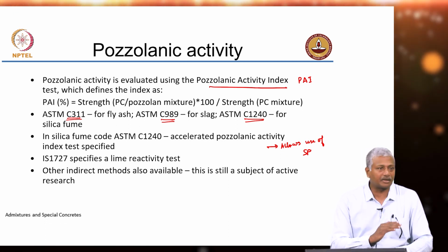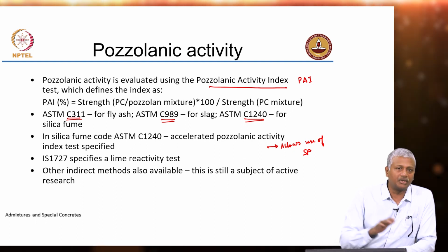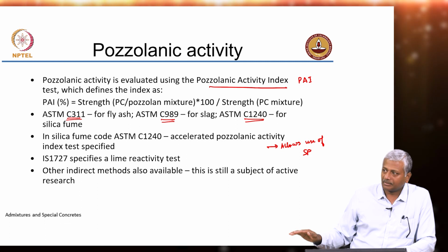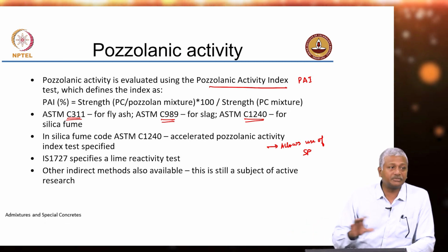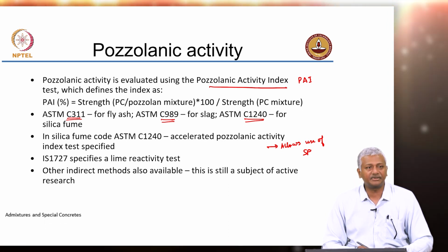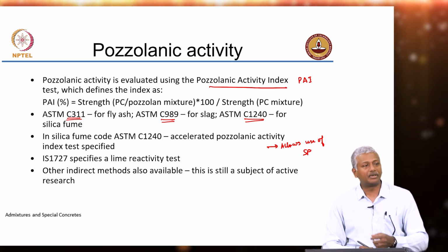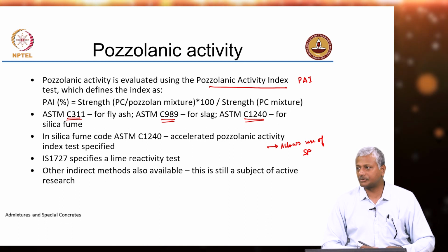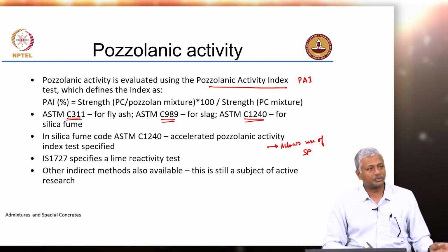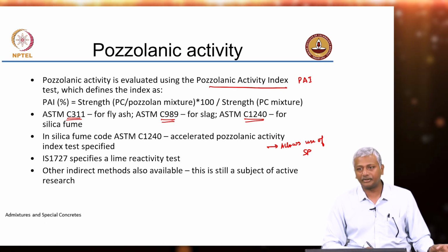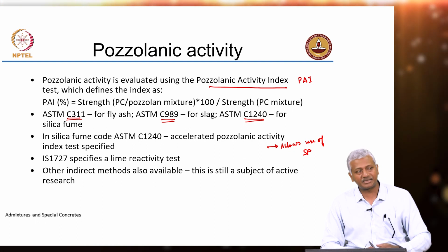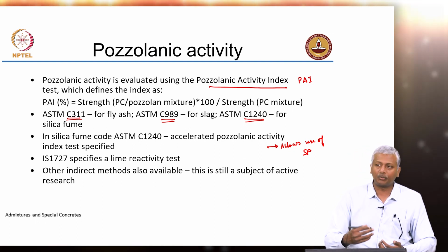So, there they are comparing at the same water to cement ratio. Here we are comparing at the same consistency. Now, that produces a lot of different results, major differences in the results that you can expect from your strength tests. So, you can't compare the way that grading is done in India to the system of grading that is done in Europe. Okay, so, you need to be a bit careful when you look at the results and understand carefully what has been done.